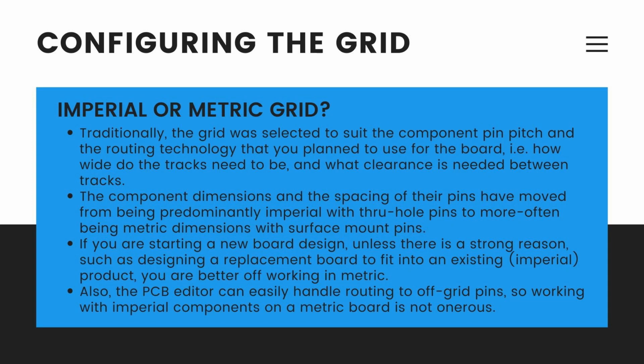The basic idea is to have both the tracks and clearances as wide as possible to lower the fabrication cost and improve reliability. Of course, the selection of track or clearance is ultimately driven by what can be achieved on each design, which comes down to how tightly the components and routing must be packed to get the board placed and routed. Over time, components and their pins have dramatically shrunk in size, as has the spacing of their pins.